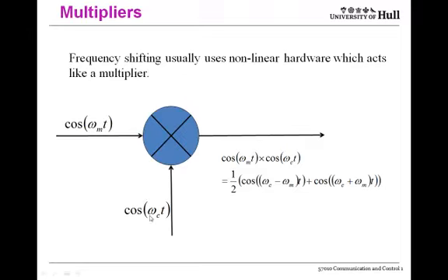Also the carrier squared and the message squared, and all powers and products of the two will appear at the output. Now the hardware multiplier has been engineered so the major part of the output is the product of these two signals, but all the other combinations will be there, and generally these have to be removed by filtering.